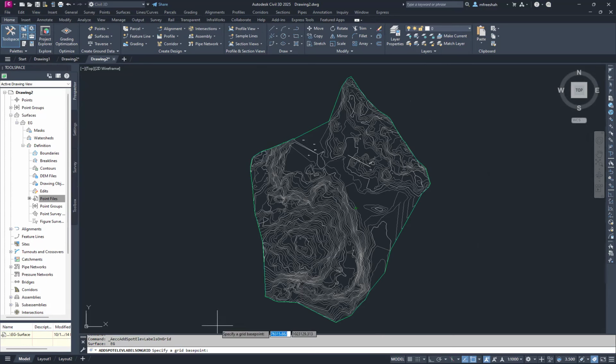left point, for example, here, and it asks you what is the, you wanted to make grid rotation, for example, with any angle, or you want it in zero direction like this, horizontal one. So if I want horizontal, no rotation, I will press enter. What about the spacing in X direction? This is X direction. Spacing, for example, 100 meters.